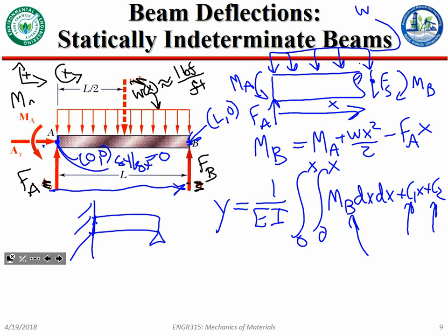So by substituting in these boundary conditions, we can solve for everything in this equation, and you'll see that as you add more complexity to the boundaries, like if I said that this end is fixed and there's some reaction moment there, well, besides the displacement boundary condition, I also got a slope boundary condition now because I've fixed that end.